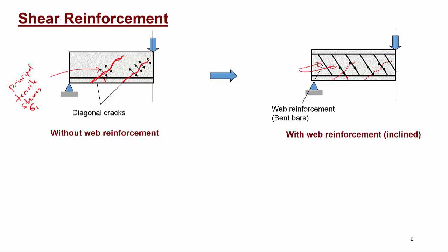In the past, this used to be achieved as follows: you have some longitudinal reinforcement on the tension side here, but in the shear span, where the bending moment is gradually decreasing, you don't need all the longitudinal reinforcement. You can bend some of the reinforcement upward like this one to get that inclined shear reinforcement as well. This longitudinal reinforcement, bent upward, will act as the shear reinforcement.